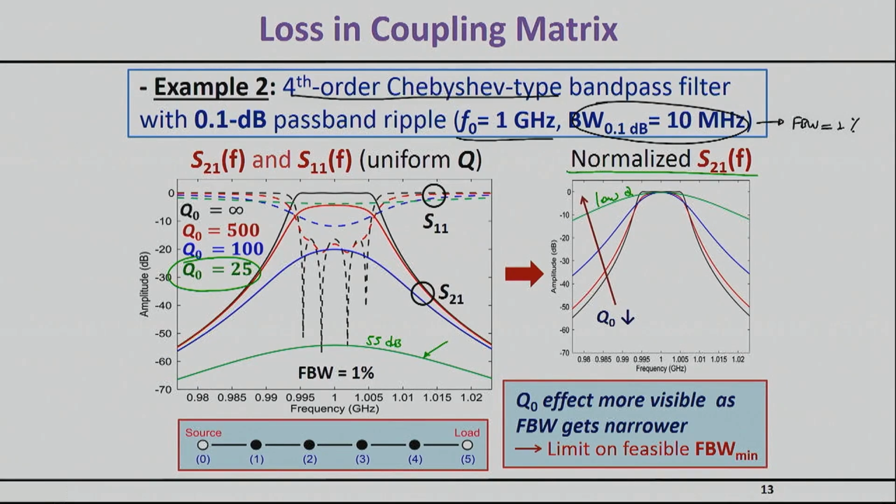So now you might start realizing more precisely why we don't do channel filtering right after the antenna. Let me remind you of some of the things we had discussed in the system level discussion. We had said that right after the antenna, we will normally select our band. Then we will down convert with our VCO, and finally we will have channel selectivity here. So channel selectivity would not be in the first stage. The first stage would be more band selectivity.